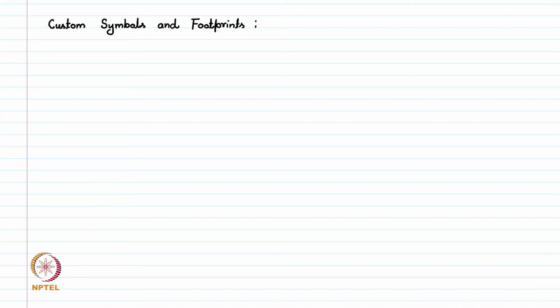That was a very small schematic, and now we want to use a custom component, a switch. In the last lecture the battery was driving this LED continuously. We want to put a switch in between so that we can turn it on and off as per our desire. So we want to develop a switch symbol and an associated footprint which we will then use in the earlier schematic and PCB, and we will see how it is done.